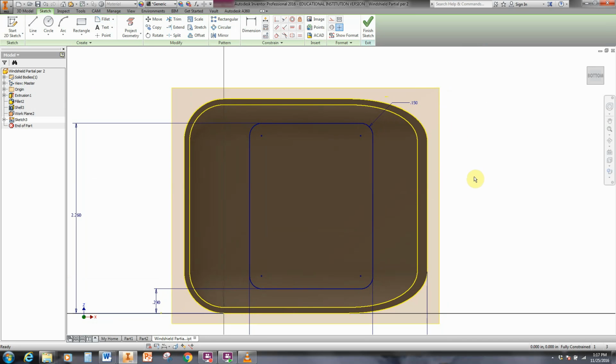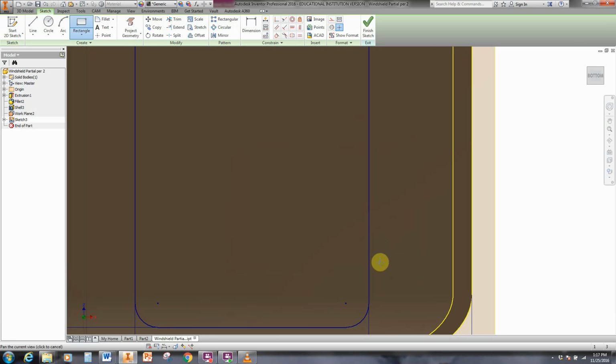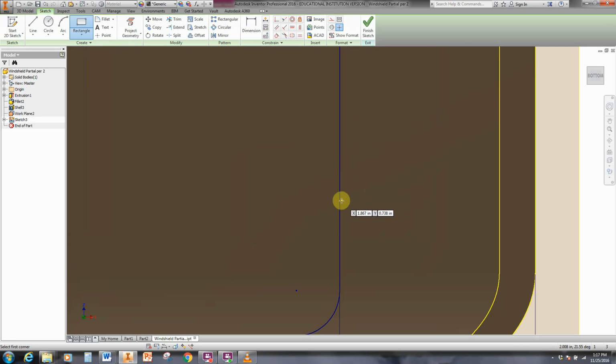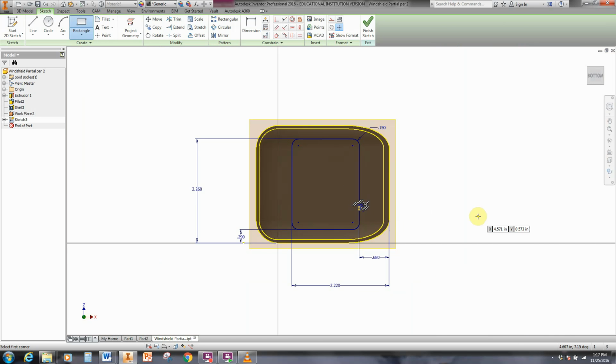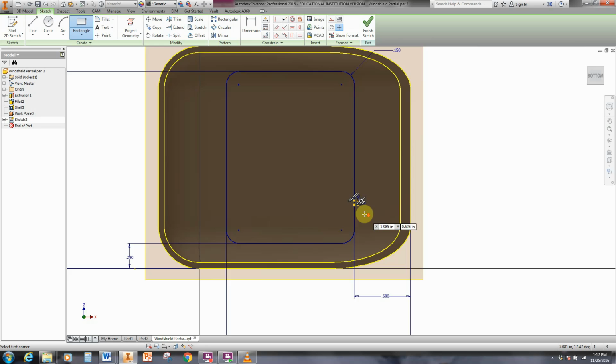Now we can go back and add those little rectangles. Those little rectangles are 0.05 wide and 0.04 out from our surface, our rectangular surface. So we click on rectangle again, and I'm just going to put them not exactly where they belong at first. Click on the line, and it sticks out 0.04, and its width is 0.05. These are very small. When you zoom way out, you won't even hardly see them. When you look at the whole thing, it just looks like there's a little constraints there, but you can hardly see the rectangle.